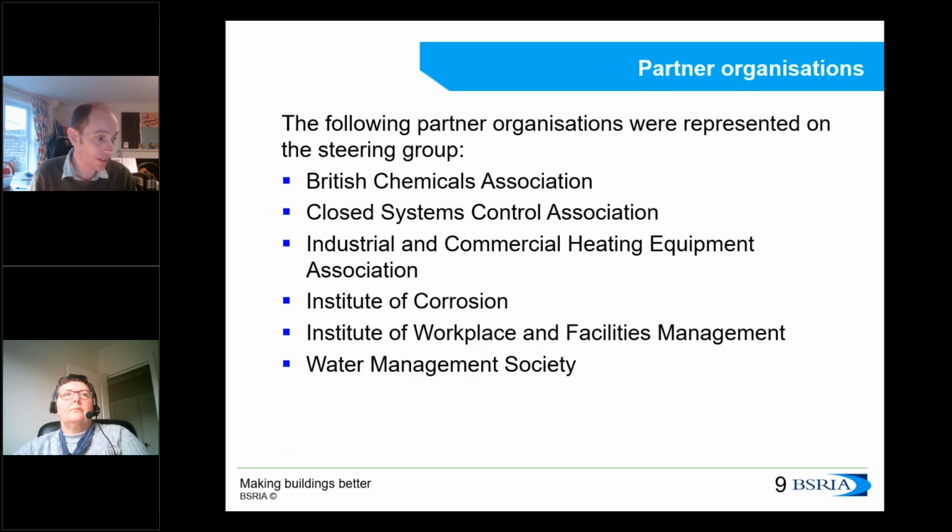Yes, and there's also the question about barrier pipework. We do mention plastic pipework in the guide. It's not that we don't mention it at all, it's that we don't have a specific extensive section on plastic pipework in the guide. We do definitely mention the issue of barrier pipework, because there are certain types of plastic pipework that permit oxygen ingress.